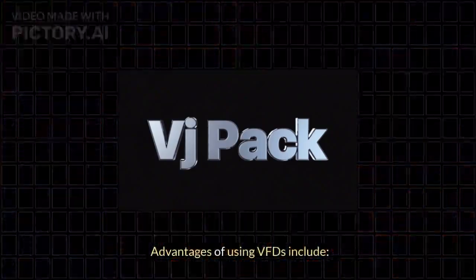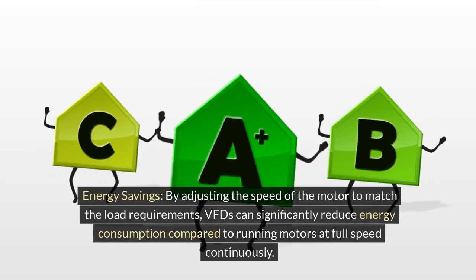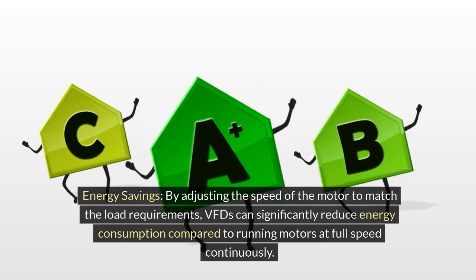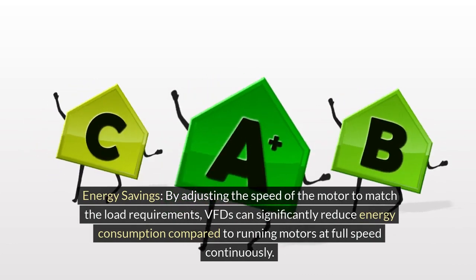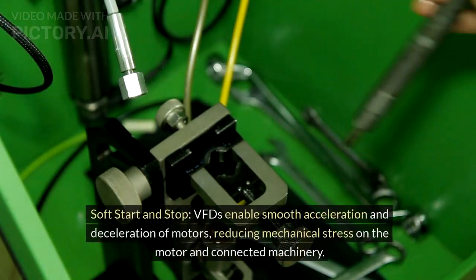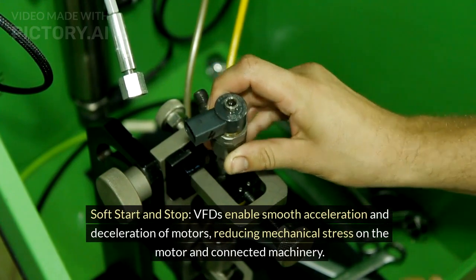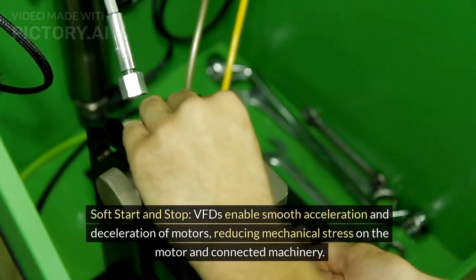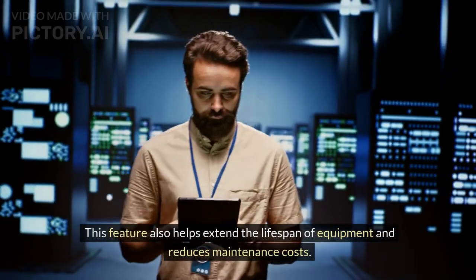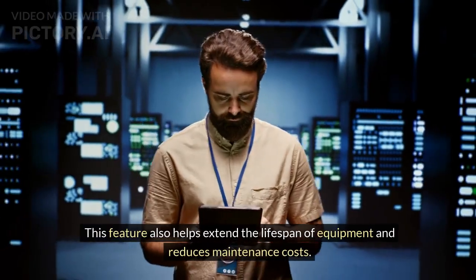Advantages of using VFDs include energy savings. By adjusting the speed of the motor to match the load requirements, VFDs can significantly reduce energy consumption compared to running motors at full speed continuously. Soft start and stop. VFDs enable smooth acceleration and deceleration of motors, reducing mechanical stress on the motor and connected machinery. This feature also helps extend the lifespan of equipment and reduces maintenance costs.